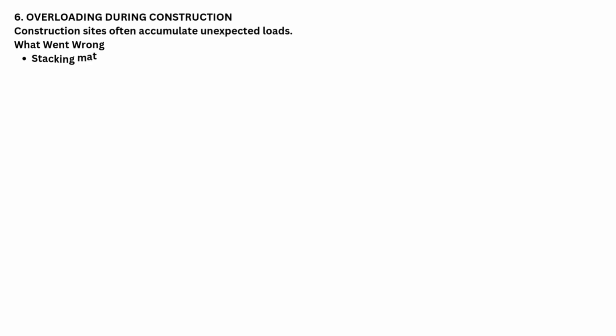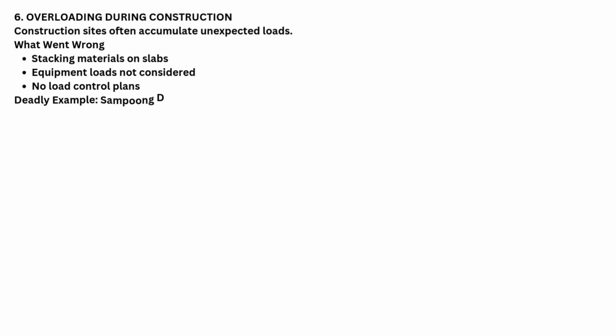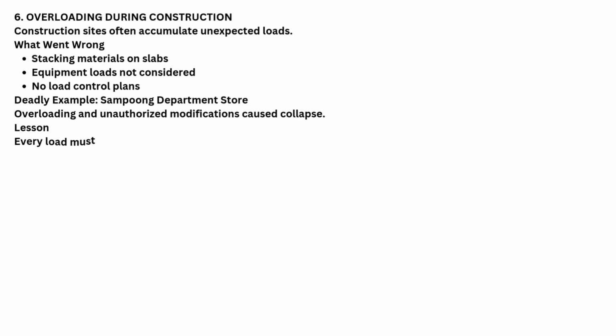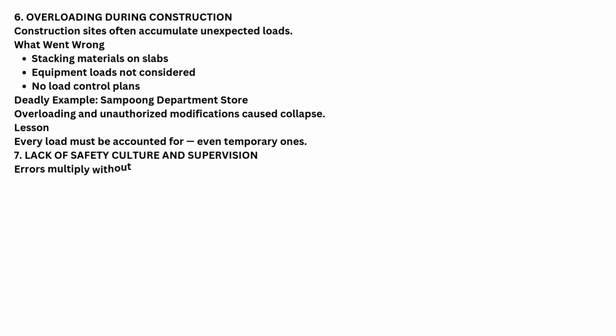6. Overloading during construction. Construction sites often accumulate unexpected loads. What went wrong? Stacking materials on slabs, equipment loads not considered, no load control plans. Deadly example: Sampoong Department Store. Overloading and unauthorized modifications caused collapse. Lesson: every load must be accounted for, even temporary ones.